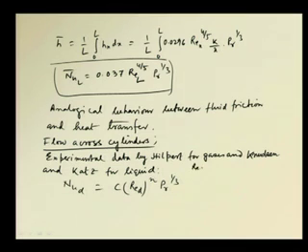For different values of Re_D: for 0.4 to 4, C is equal to 0.989 and n is equal to 0.33. For 4 to 40, C is 0.911 and n is 0.385. So C is more or less constant in the initial stages.